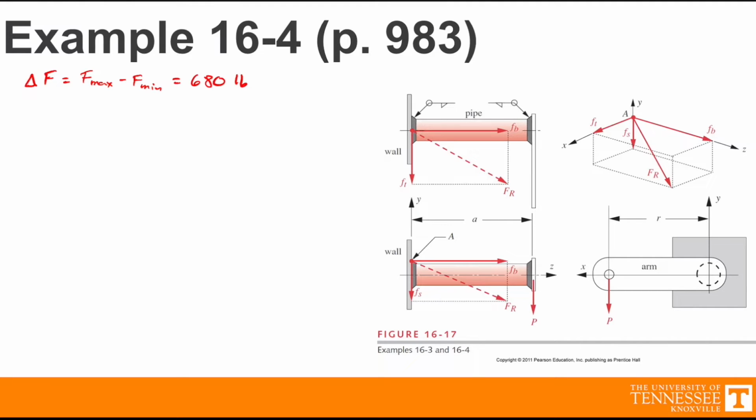Like we said, this is a category C, but since this involves weld metal, we also need to check for category F. So we're going to start by checking to see if we are limited purely in the weld metal, and then we'll check the actual joint to determine which is going to limit us most, the joint or the actual weld metal. So the first thing we need to do is figure out what kind of loading we have. We've got three different loads in here. We've got a shear of just that whole weight pulling down on the weld.